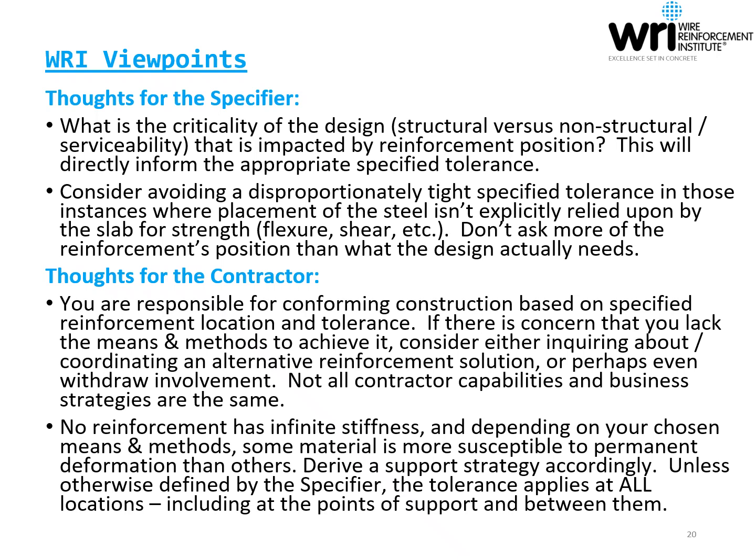And in another instance, if the design criticality is such that the tolerance on reinforcement location is stringent, just know that smaller diameter reinforcement material will almost certainly require a more robust system of support in the field, and that there might be other welded wire reinforcement sizes and patterns that strike a superior balance between design intent and constructability.